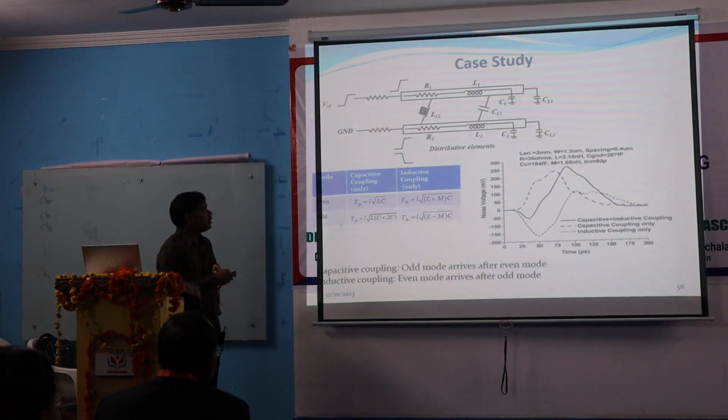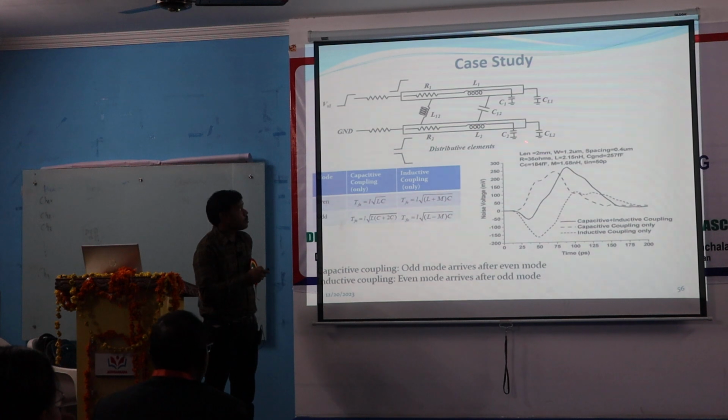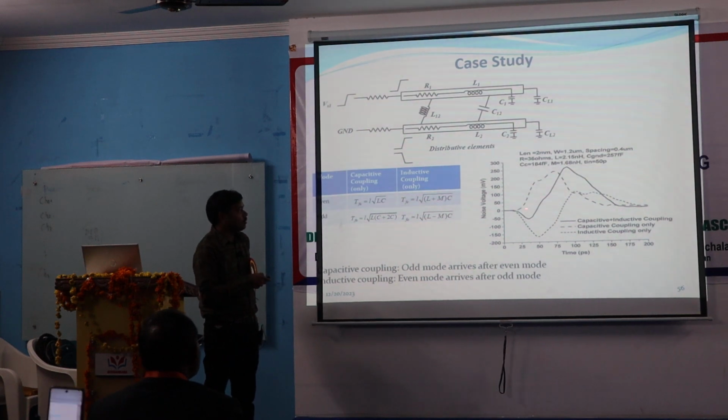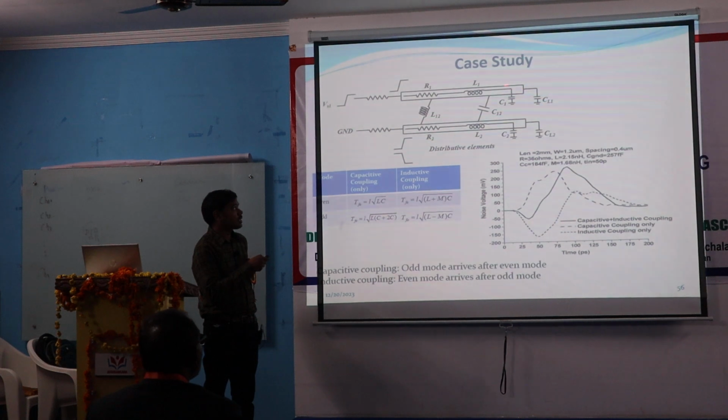Now you see what is happening. There is a change in the signal, it is rising. Line 2 wants to stay stable at 0, but it is not stable. You can see some noise is being induced on the line. This is the noise we are talking about, the noise created on the second line due to the signal transmission on the first line.